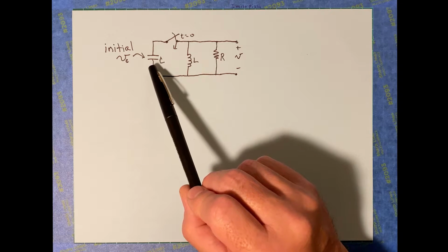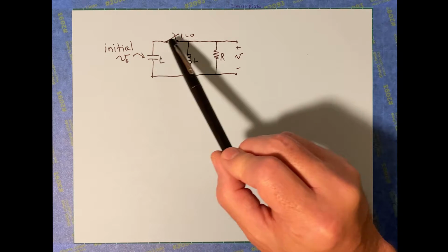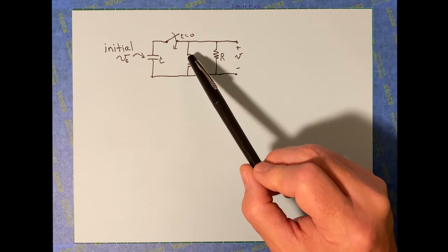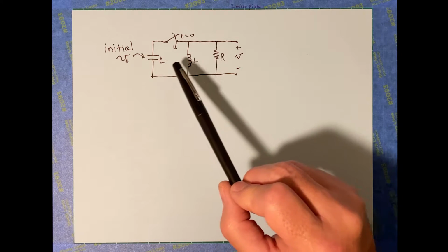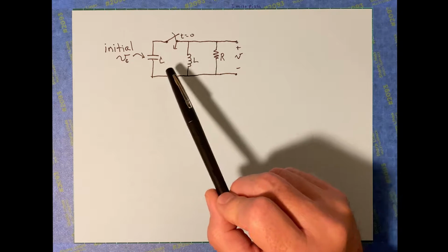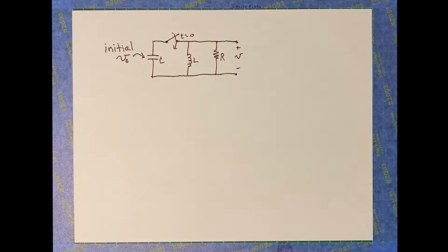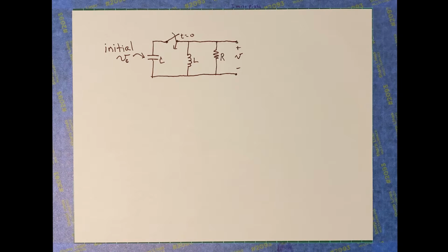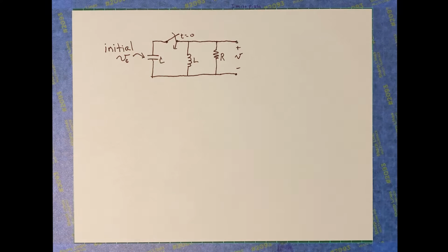However, the capacitor doesn't maintain that current forever. Eventually, it's going to use up all of its energy. That means the magnetic field inside the inductor is going to start to decay, and there's going to be a little bit of oscillation between the capacitor and the inductor. You'll see how all of these things work together, but keep in mind, this is probably not anything that we've seen so far in this course. Okay, so natural response, parallel RLC, and everything's got the same voltage across it.